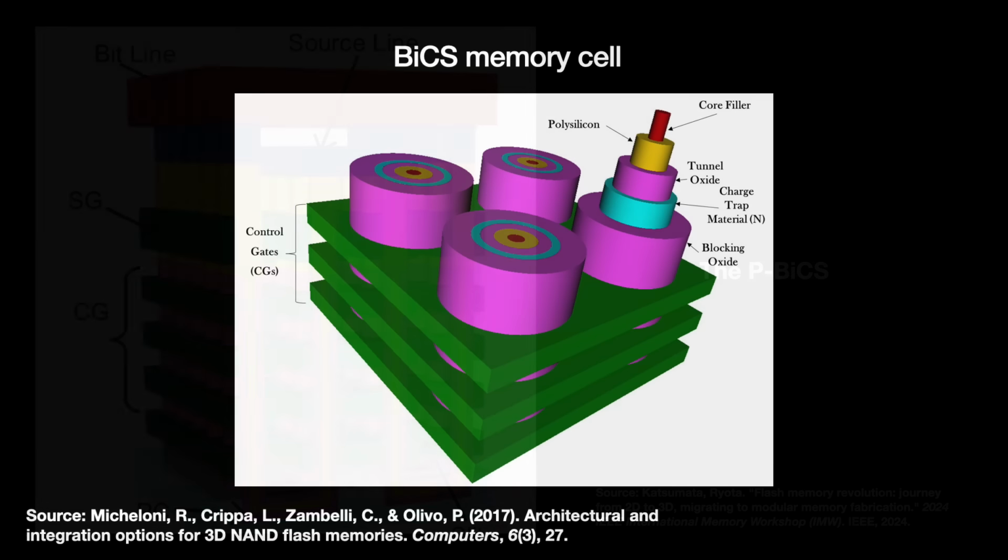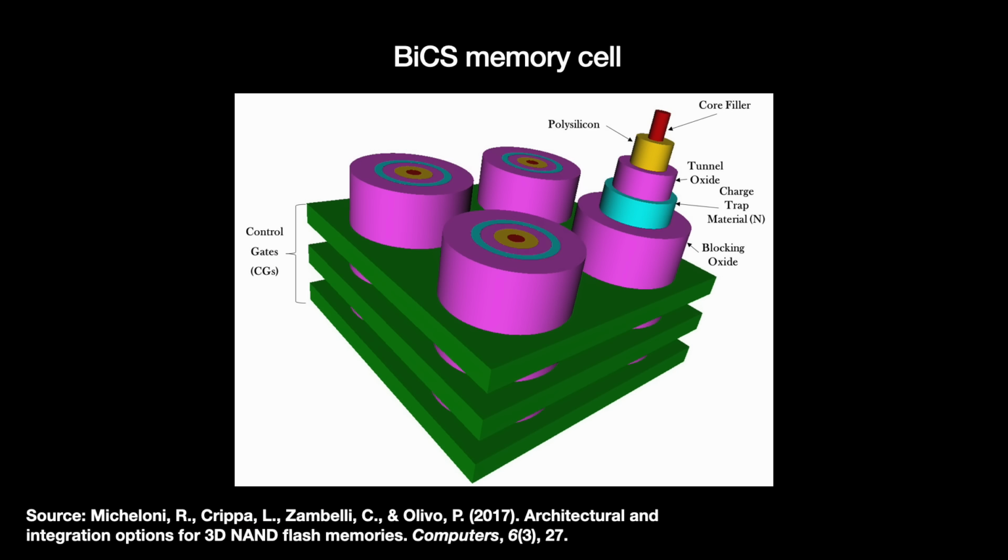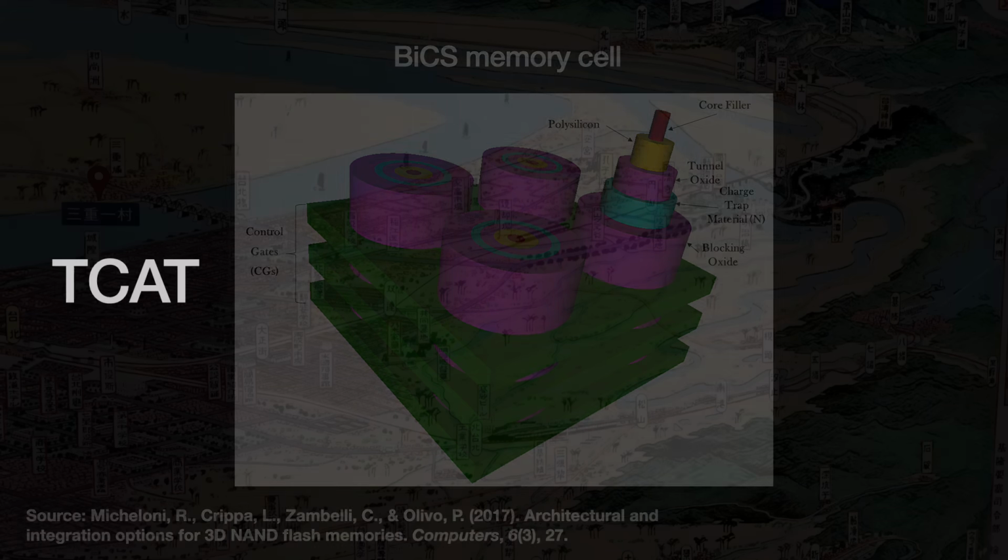Metal would be a far better gate material than polysilicon, but Toshiba chose polysilicon for a reason. They needed a material through which they could etch both deeply and cleanly, and metal is definitely not good for that. So what to do? In the end, NAND leader Samsung won the race.